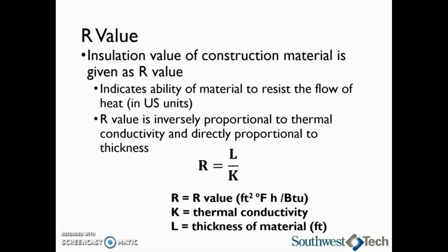However, whenever we are talking about an R value, we just say R whatever the value is instead of using the actual units. Again, the R value will be in US units, so the thermal conductivity will be in BTU per foot degree Fahrenheit hour, and the thickness of the material will be in feet. Let's take a look at an R value calculation.